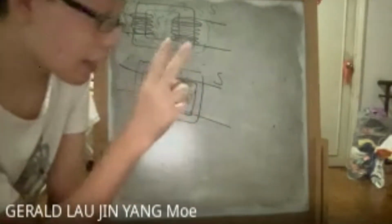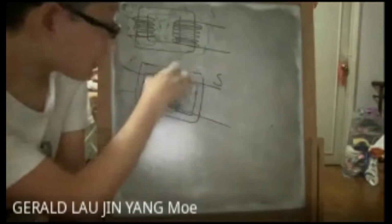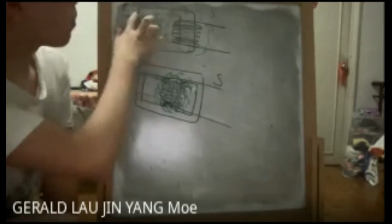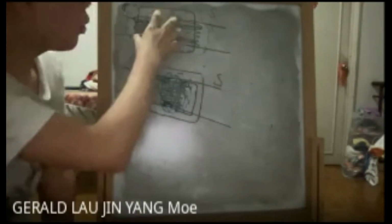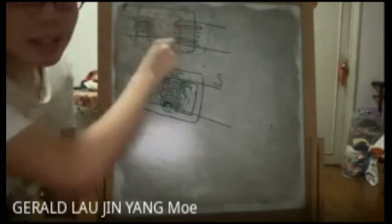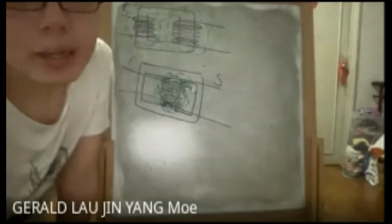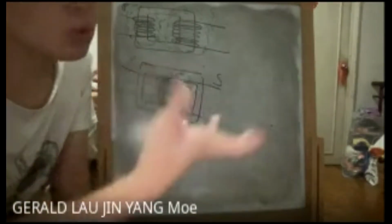Okay, the second factor is eddy current. What does it mean, eddy current? Changing magnetic field induces eddy currents in the iron core. That means besides your primary current inducing a secondary current, you also will have additional eddy currents at the side. This eddy current heats up the iron core. That's why it will release more heat energy to the surrounding. That's why you will lose the energy.